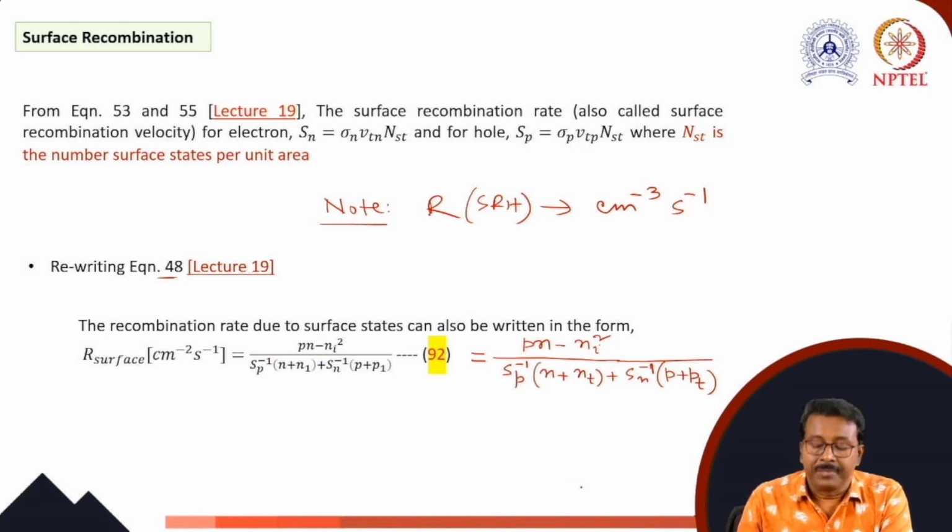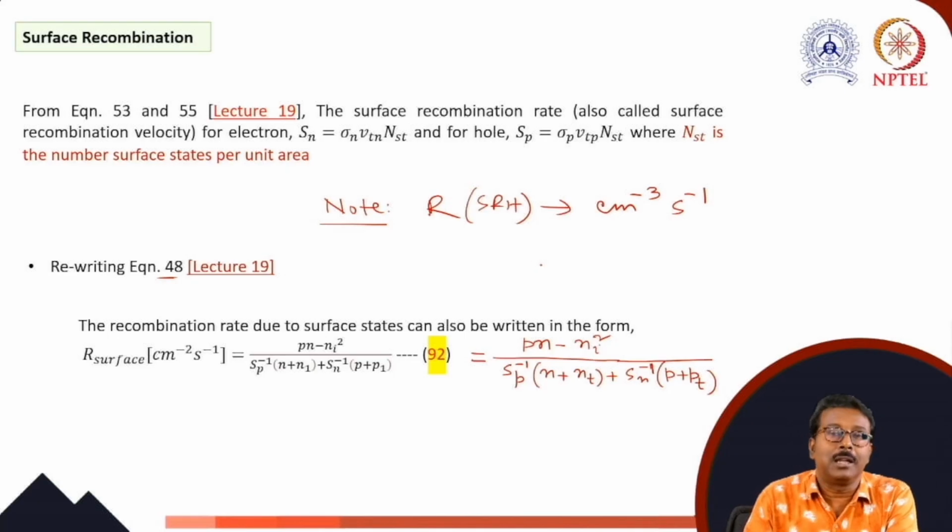And finally, besides the surface recombination, the bulk recombination due to SRH, if there is bulk recombination due to Auger recombination or due to some other radiative recombination, all you have to consider for accurate modeling of a solar cell.